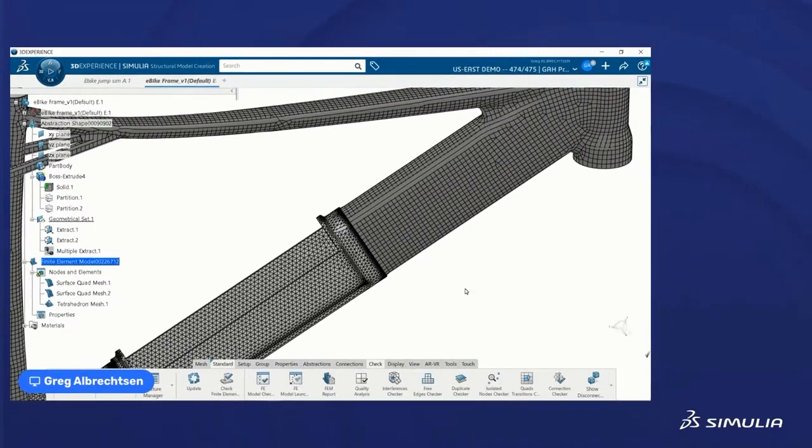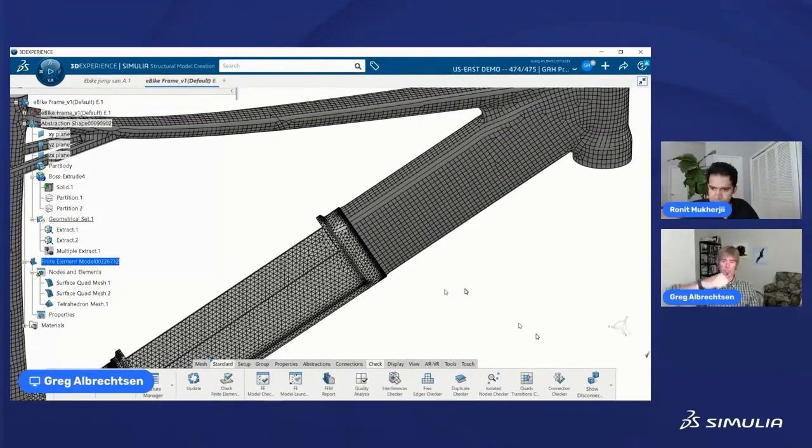Now, if I had a block, and I had just a single plane come into the corner of that block, and I don't have a way to control that rotational degree of freedom, it's going to act like a hinge. It's just going to fall. It's going to flop. So you need to capture that rotation to get that displacement transfer from that shell mesh over to that solid mesh.